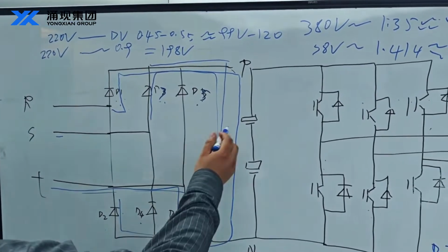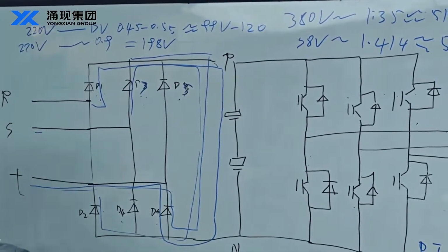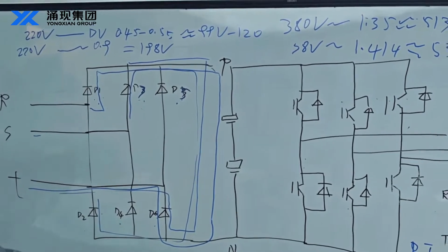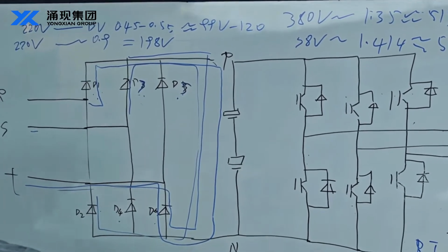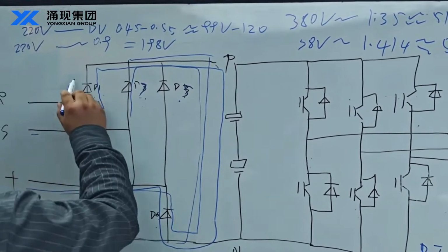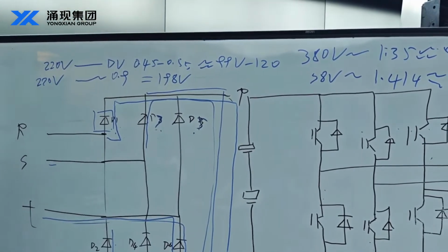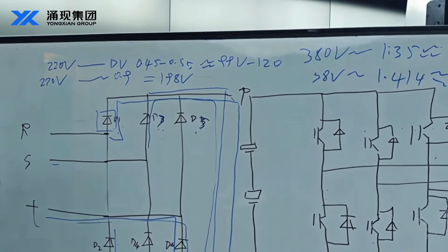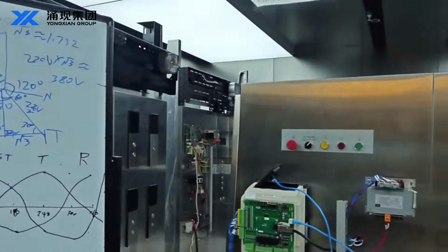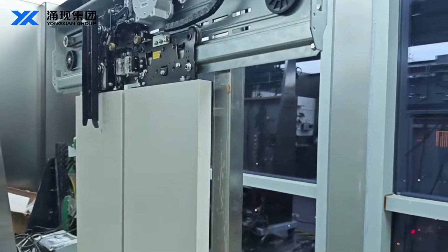This completes one 3-phase rectification process over the full 360-degree cycle. So how do we measure these diodes? When measuring rectifier diodes, we can sometimes use the diode test function on a multimeter to test the following pairs.